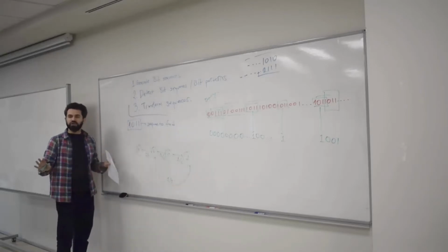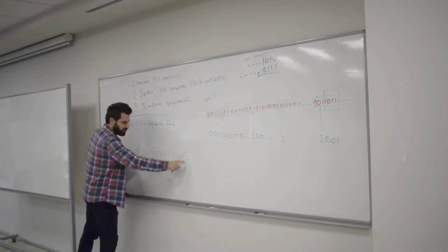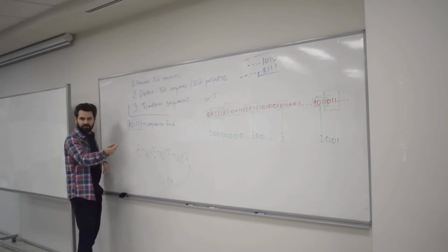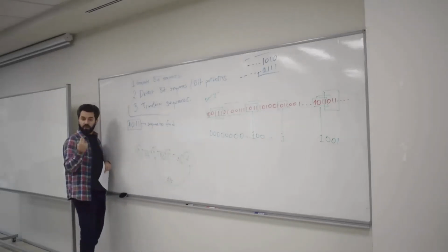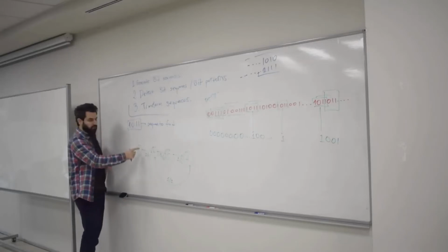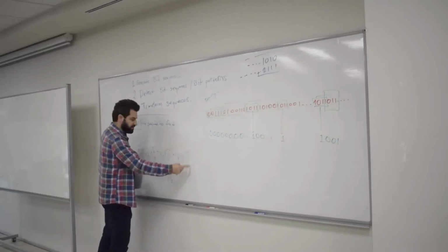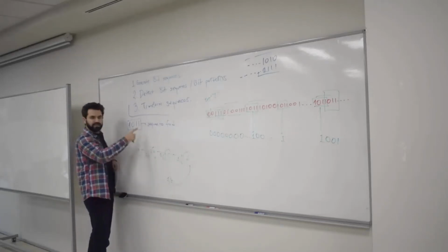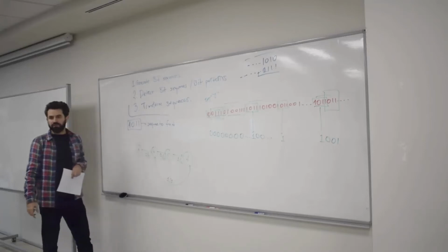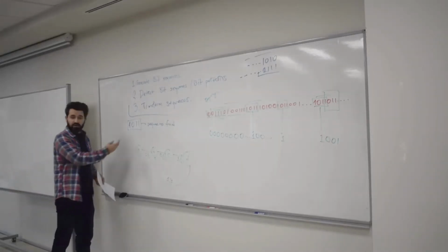This is the most crucial part of drawing the finite state machine. All right? Because now you actually completed a detection path. This is the detection path, actually. In order to detect that sequence, your input has to follow the following path. It has to go A to B, B to C, C to D, and D to B and back again. Okay? In that case, you have got the detection pattern. However, this is not over. We're not over, because we've got other possibilities.